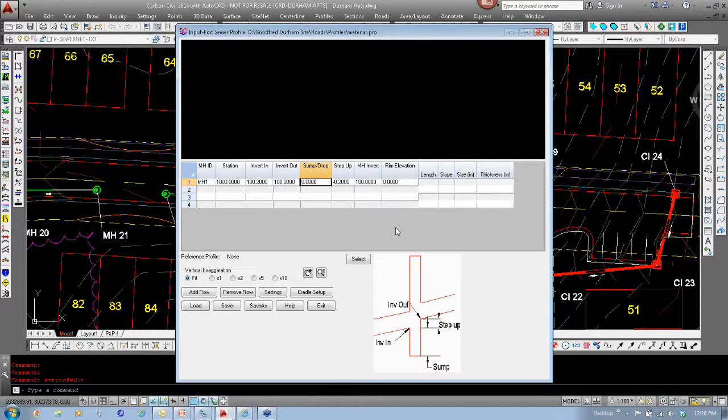You certainly can if you want to. Here where I'm located, we don't use those too often. Your manhole invert, the rim elevation, we'll just make it 105. And you basically enter in your manhole information on line 1 and 3. And then the middle line will only refer to the pipe length, slopes, and some of those options get filled in for you.